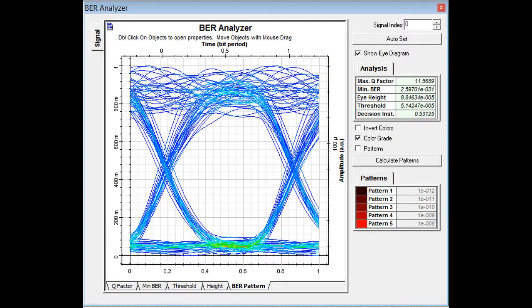For result and discussion, the system is analyzed under a clear condition with an input power of 20 dBm, the bitrate of 10 Gbps, and at a range of 40 km. The eye diagrams of this system under clear conditions are as shown in this video. This system exhibits a better Q factor and low BER under these atmospheric conditions. The attenuation effects from these disturbances can be minimized by the Co-OFDM modulation with polarization.